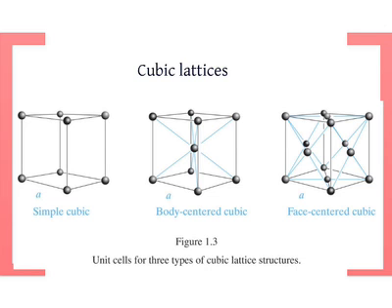We have what's called a simple cubic lattice, which is the simplest possible lattice. You have a cube, an atom at every corner of the cube, and you repeat that cube. Very straightforward. That's sodium chloride, salt. That's the lattice. You can have a body-centered cubic lattice, which is exactly the same as the simple cube, except that now you have an atom in the center of the volume, the body of the cube. It's body-centered cubic, BCC.